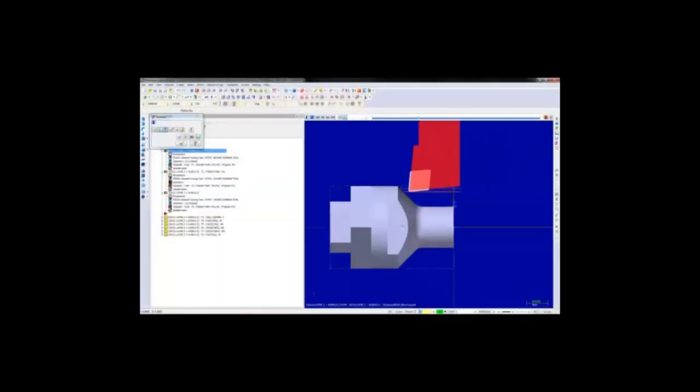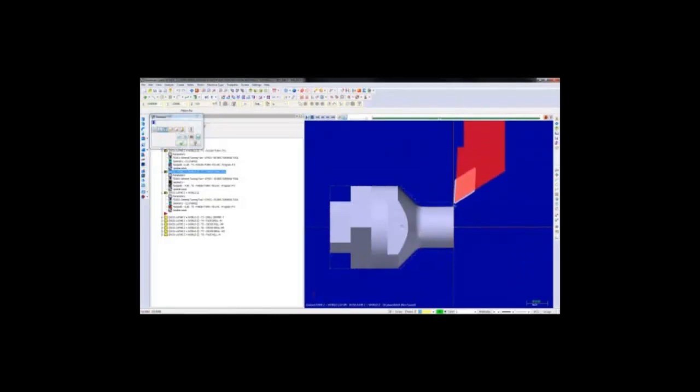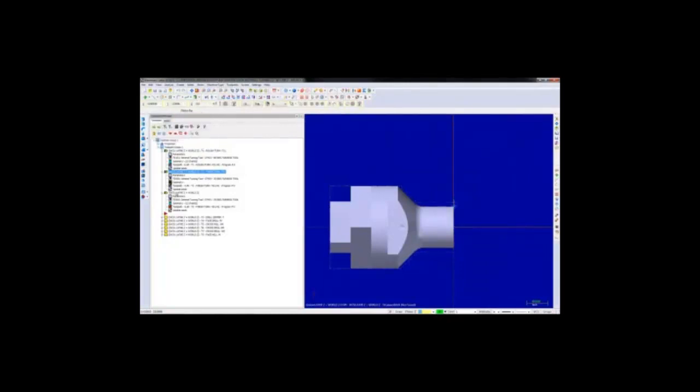In this particular slide, what we're going to see is a simple Mastercam turning project. We're turning, facing, and finish turning. What I like to show here is even if you have a simple seat of Mastercam for a standard lathe, maybe you don't have the multi-lathe package, you can still use that for your upper turret, main spindle, and you can move and drag those toolpaths around anywhere in the machine, as you'll see in a later slide.